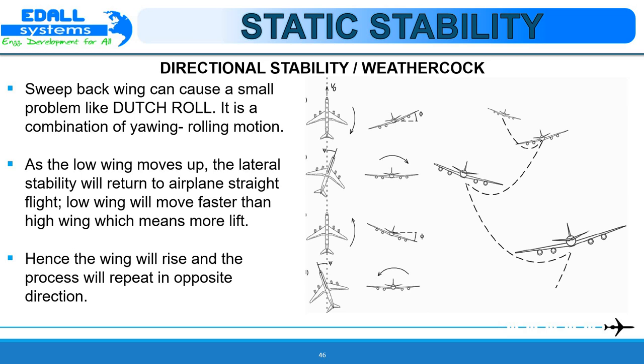The Dutch roll mode is also called so because the motion of the aeroplane following its excitation is said to resemble the rhythmical flowing motion of a Dutch skater on a frozen canal. One cycle of a typical Dutch rolling motion is shown in the figure here.